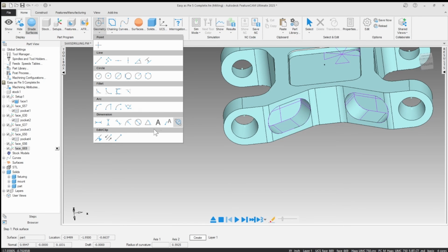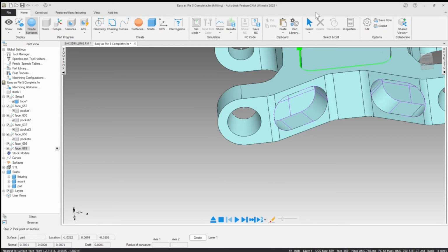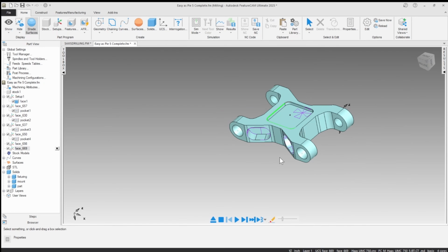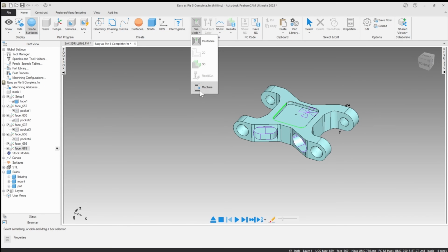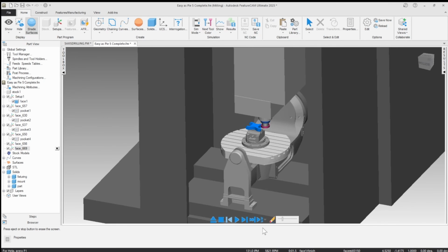So if we check that curvature again, if you look at the bottom here, axis 2 is showing, yeah, that axis is changing. So it's tapered, and that's why the 5-axis make IFR didn't find it, because it's not a 2D feature, right? So we could surface mill those and go on. Anyway, let's go ahead and finish this video up. Let's go look at the machine sim for all this. Just as a reminder, we want to check for any gouges.